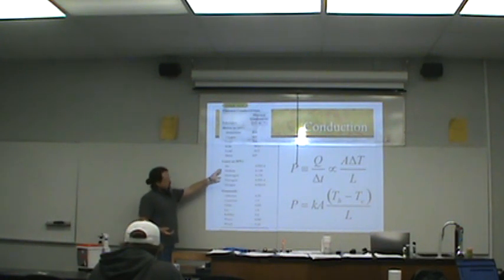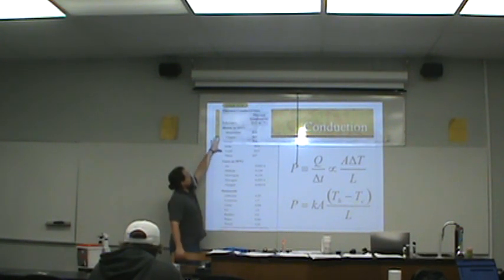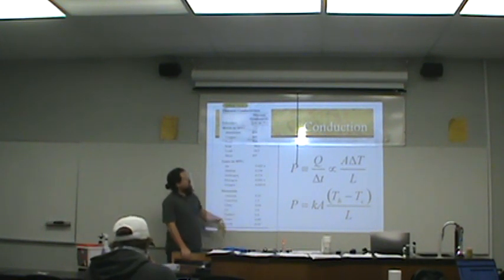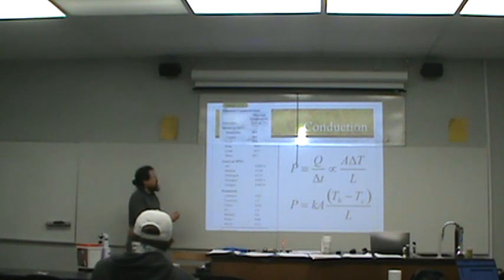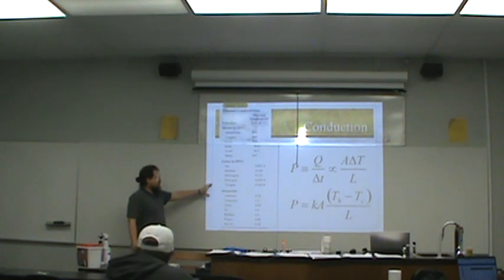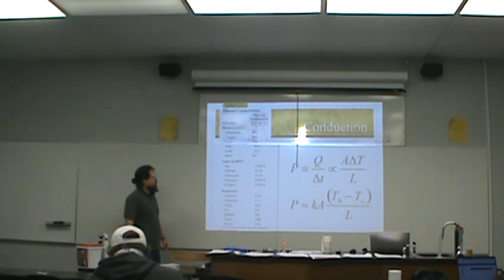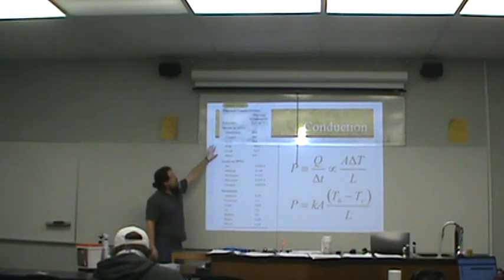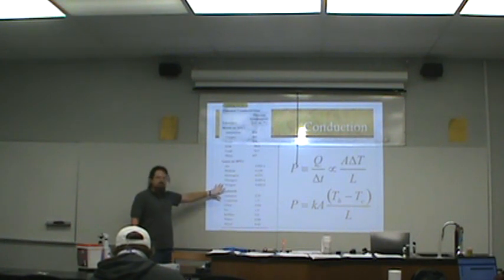And just looking at each section on this table, we have items that are metallic, and at room temperature, they have relatively high thermal conductivities. It's units of several hundred. Compare that to the gases and the non-metals, whose thermal conductivities range anywhere from 2 to 0.02. Compared to the metals, barely any thermal energy transfers through these things.